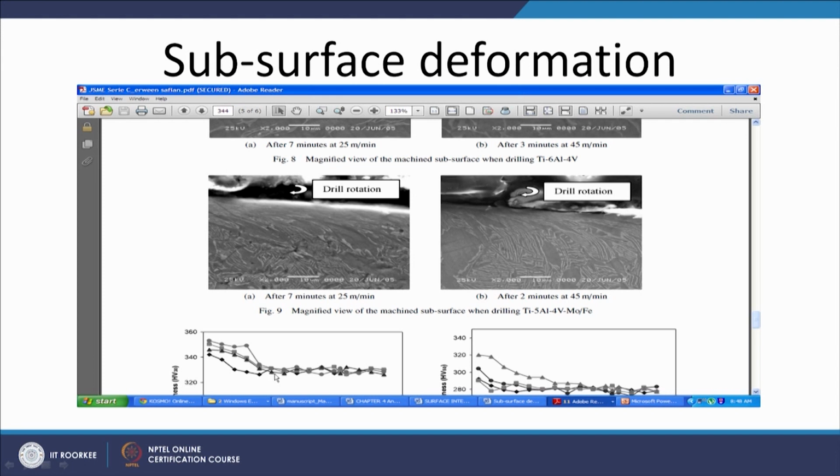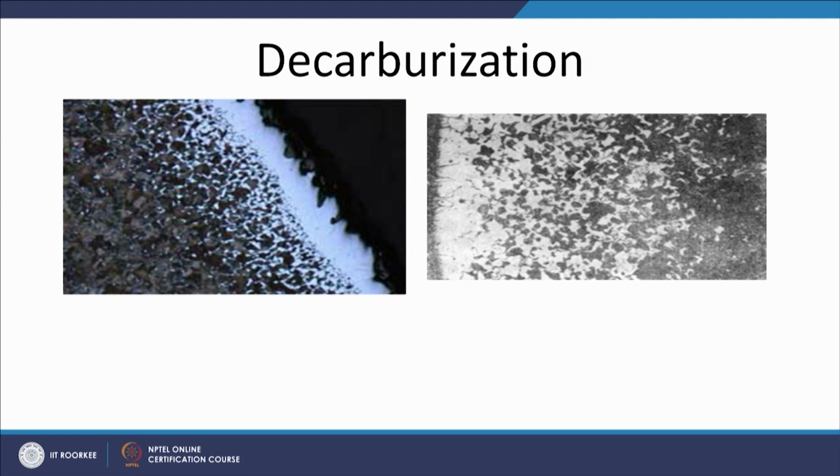The hardness variation at the surface of the hole also indicates that the surface has been deformed. Not just the hardness variation, which indicates work hardening due to deformation, but the microstructural study also indicates that the surface has been badly deformed due to abusive grinding. This is also the typical nature of machining processes, where surface layers are deformed.